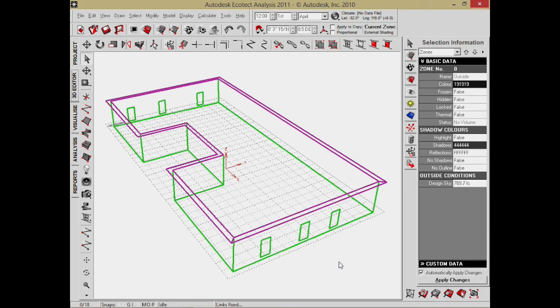You'll notice that as we're looking at it here, it has really two zones. There's one zone which is the big conditioned space. There's another zone which is just this little bit of overhang, that's considered a shading surface. So it's in here now, and we can go ahead and analyze this space. Again, we can look at the thermal properties, but that's not what we're going to look at today. Today we're going to look at just the issue of the daylighting.